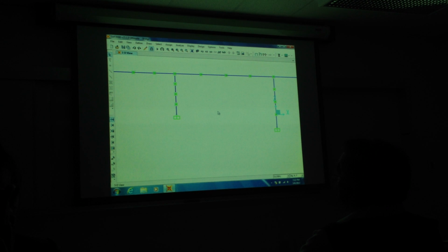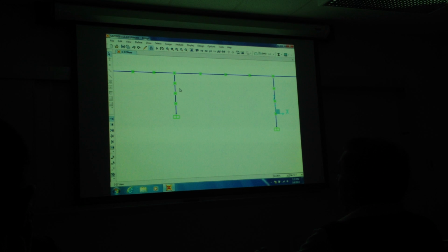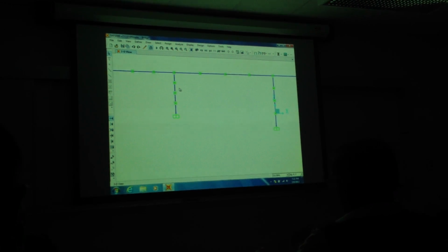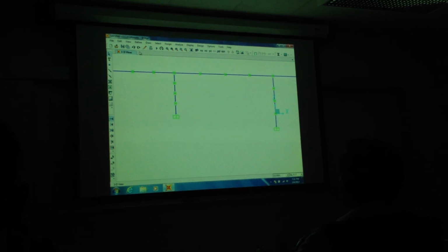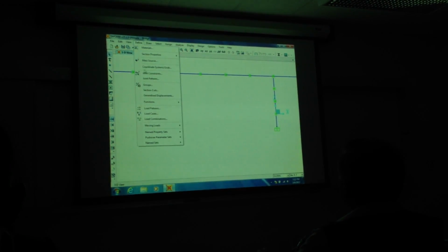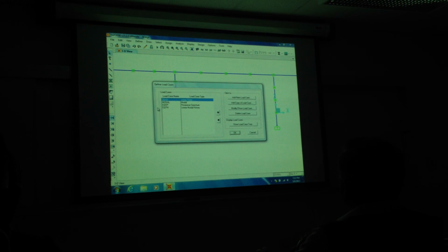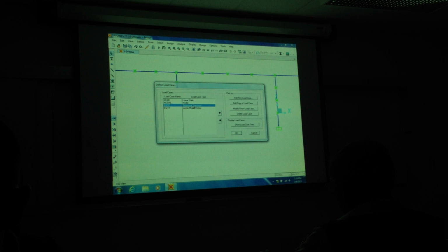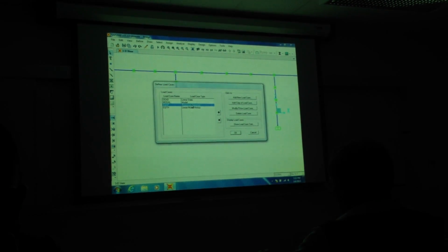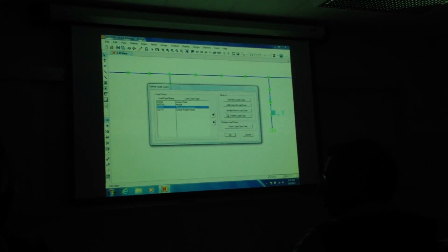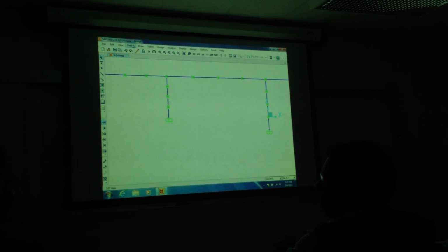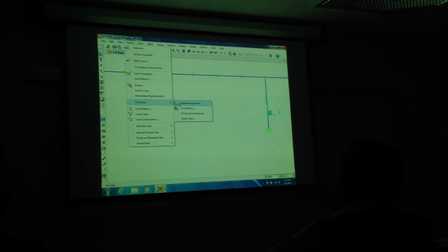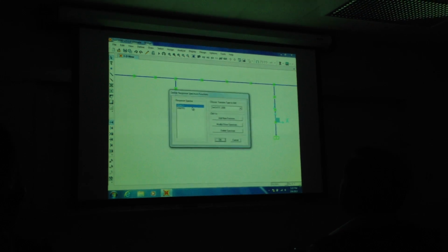Then what I want to do is run this, rather than a time history analysis, with that ARS curve and compare it to the maximum responses and moments we just got. Okay? So I'm going to unclick that, say Define, Load Cases. Go back to the response spectrum analysis we did before, and we'll use a different response spectrum curve. To do that, we have to go back to functions. Define, Functions, Response Spectrum.